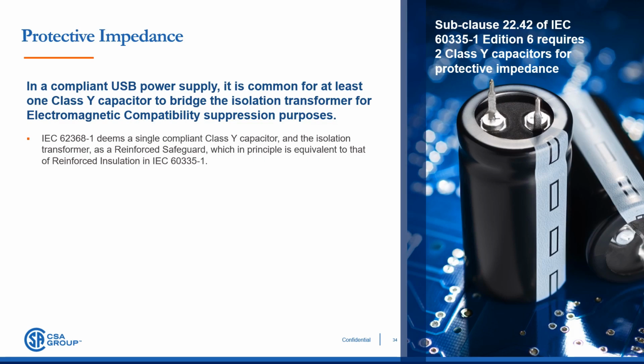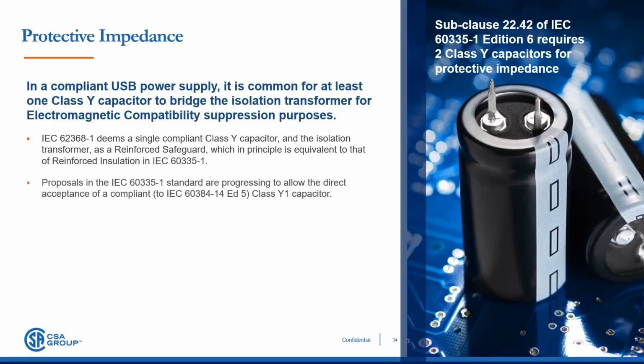Proposals in the IEC 60335-1 standard are proceeding to allow the direct acceptance of a single compliant Y1 capacitor. This is based on the understanding that such components do not short-circuit when they fail and meet the rigorous component test program specified within IEC 60384-14 to verify this. If this proposal gets accepted, there will be no abnormal operation requirement to consider shorting across the isolation barrier.